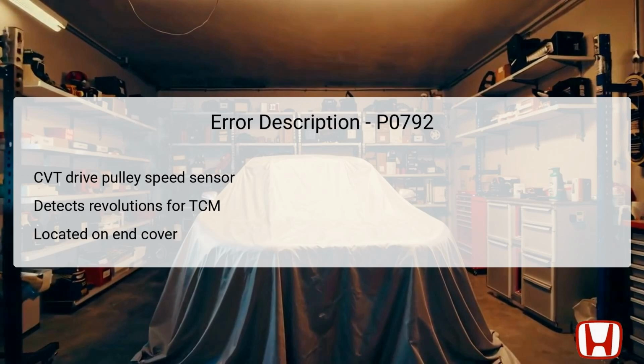This sensor is an essential component located on the outer section of the transmission end cover. Its primary function is to detect the number of revolutions of the gear on the drive pulley. The CVT drive pulley speed sensor sends a pulsing signal to the TCM. This information is crucial as it allows the TCM to convert these pulses into an accurate reading of the drive pulley speed.